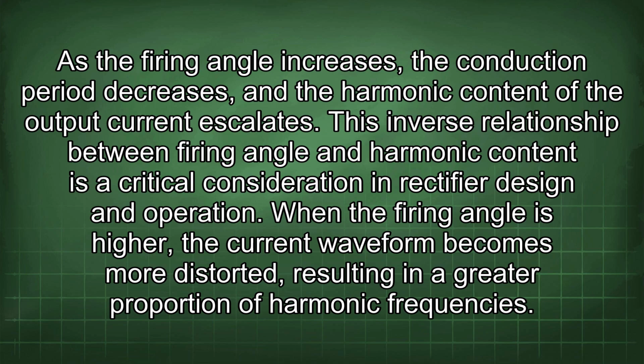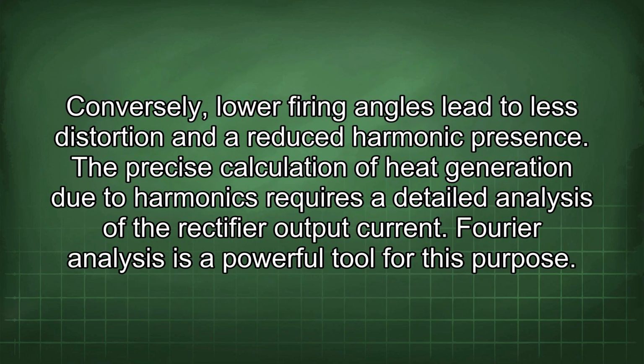This direct relationship between firing angle and harmonic content is a critical consideration in rectifier design and operation. When the firing angle is higher, the current waveform becomes more distorted, resulting in a greater proportion of harmonic frequencies. Conversely, lower firing angles lead to less distortion and reduced harmonic content.